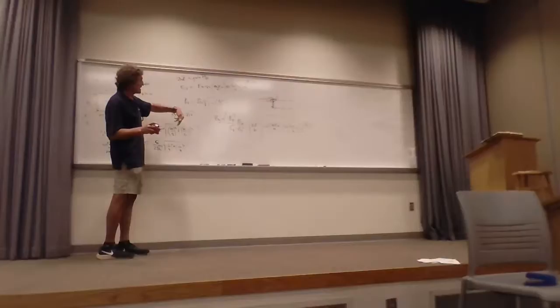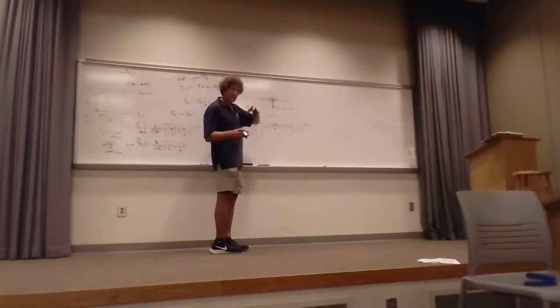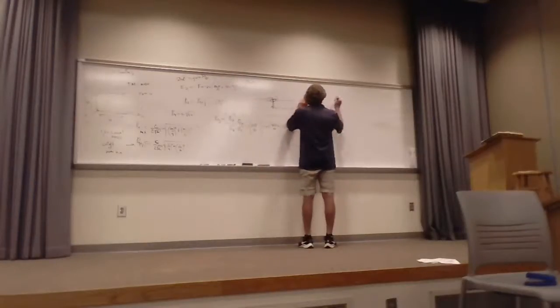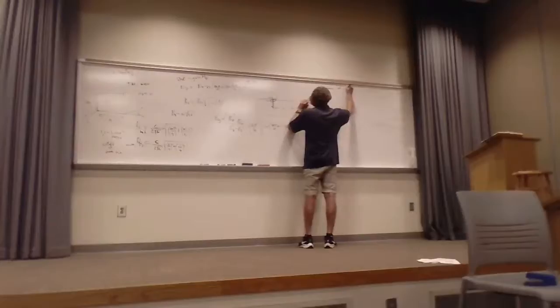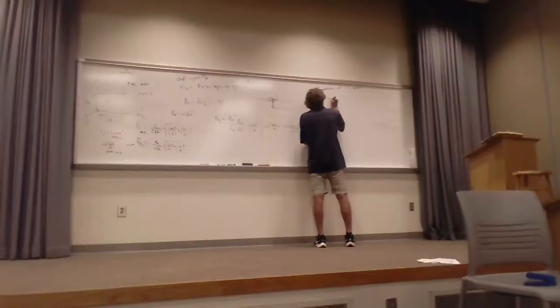And now the next thing we have to do is find the actual characteristic impedance that you would feel if you fed that. And the symbol is Z. So this would be the impedance of the guide. Impedance of TM modes. And it's Z_TM for m comma n.